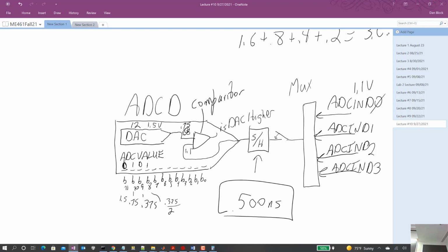And actually, what we're going to do in lab, I'll get to that more next time. Let's just continue here. We're going to have a PWM channel tell the ADC when to start. You can actually have the CPU timers do it also. You could have the CPU timers be a trigger for this ADC unit to tell it to convert.